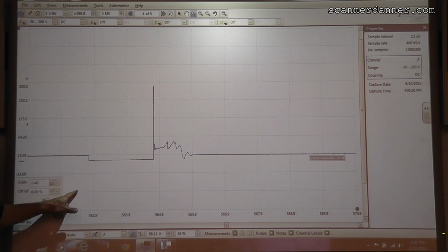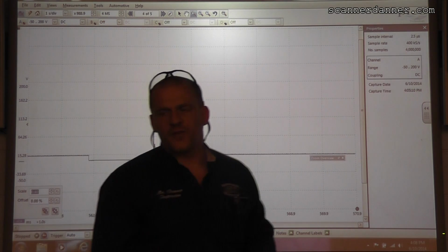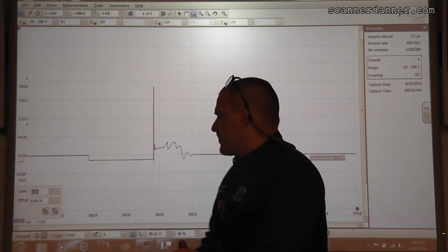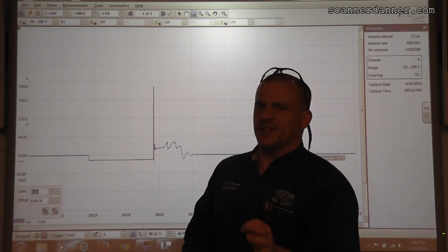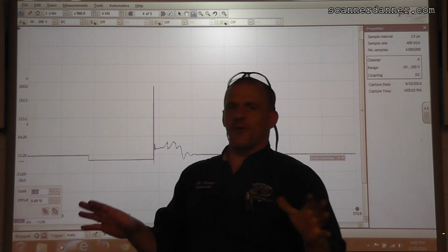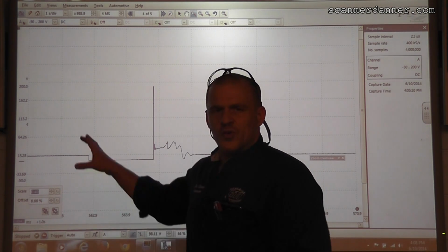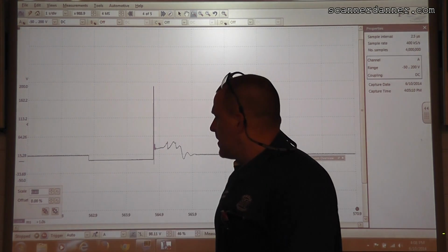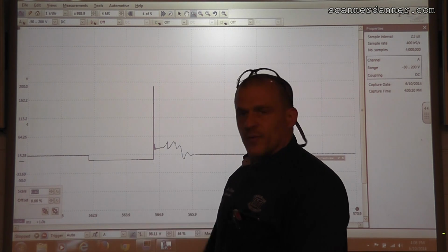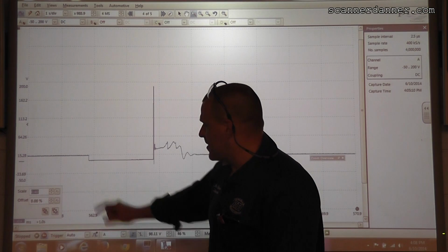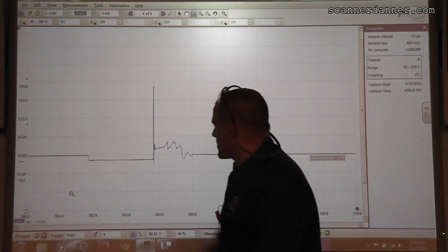So that's pretty cool. If you guys want an example of where I used this extensively, you can take a look at my Hummer series that I did. And in particular, part 6, where I was feeling my way through in-cylinder pressure transducer testing, and I really used these scales a lot, and really didn't even know those were there for as long as I've been using the scope. So that's pretty cool, this horizontal vertical scaling.